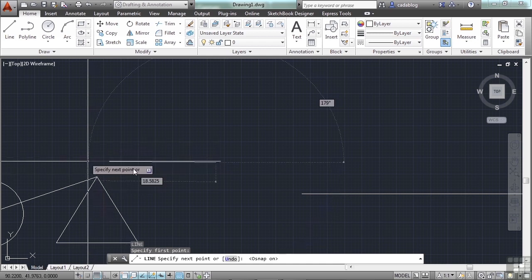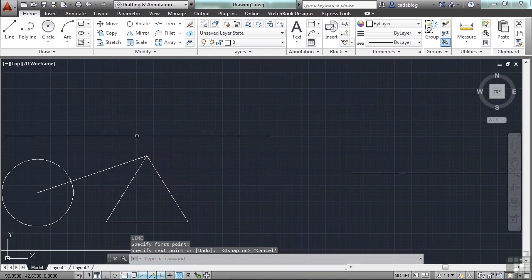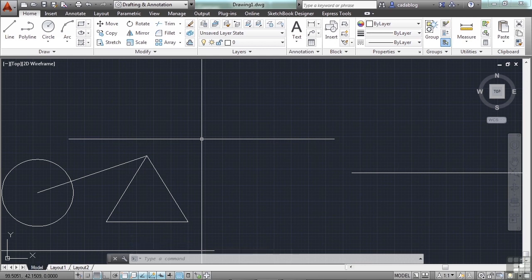Now it will take the line and follow it and project it, whichever line it is I'm drawing from. And so I can go or snap to places that don't exist but are sort of inferred or arbitrary. So that's a very useful tool as well. Again, these tracking devices, the polar tracking and the O-snap tracking, we'll talk about them later on in more depth in a section. But the function keys turn on and off these certain tools that allow you to draw more accurately or draw better even. Make sure to watch the video pertaining to each of these tools for more in-depth descriptions for them.